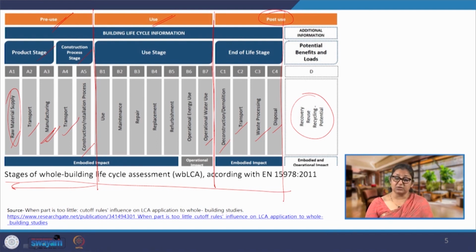For multi-storied buildings, we can't be using very heavy materials, we cannot be making very thick walls, while if we have buildings which are horizontally spread and only on ground floor, where land is not as difficult to obtain, where we have availability of land, there heavier materials can be used which have lower GHG. But the moment we are looking at vertical buildings, there the lighter materials, most likely we are going for synthetic materials or metals, they will always have higher embodied energy. A lot of energy is consumed during the manufacturing, which implies that a lot of emissions must be taking place.